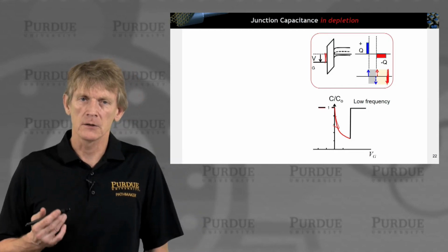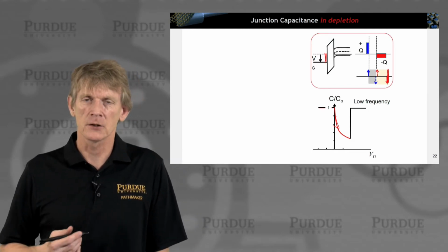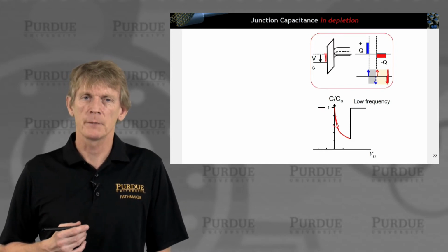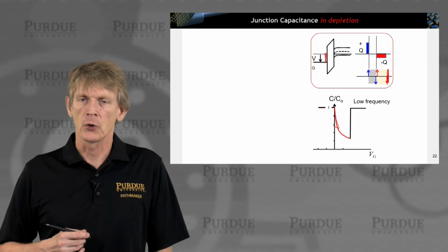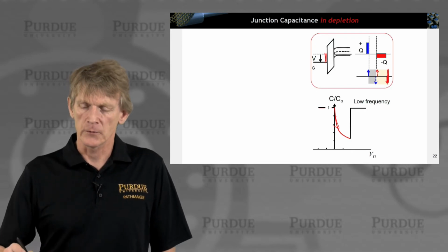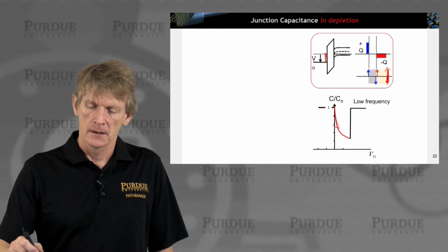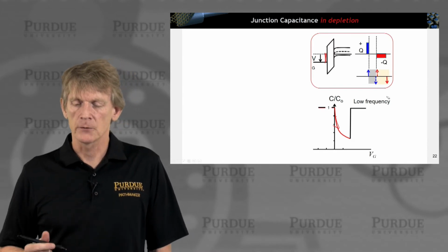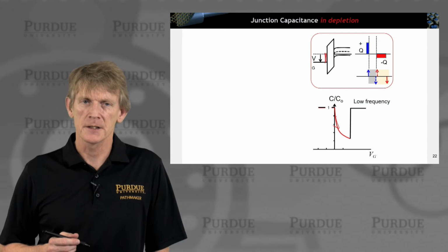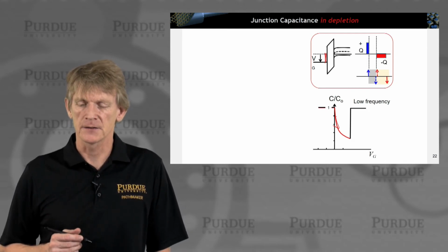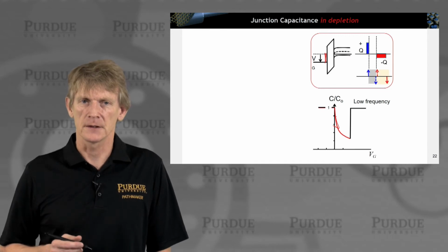Okay, we're effectively only looking at differential charges because we're looking at a small signal response. We're not looking at the total charge in the overall system. We're varying charge here at the tail end. Okay, but we have a negative acceptor charge, and we're adding and subtracting some of that charge at the tail end in the semiconductor at a certain distance.